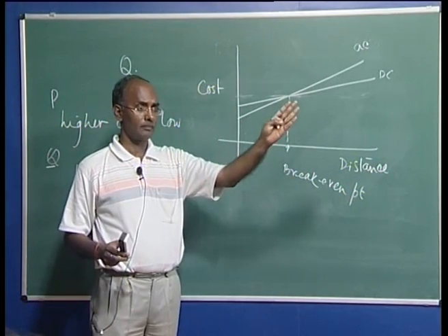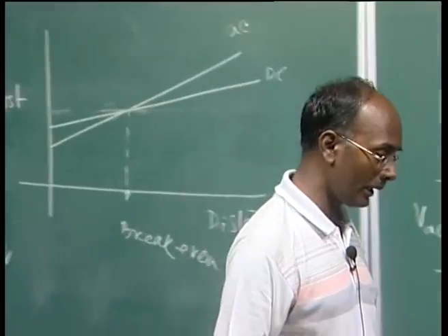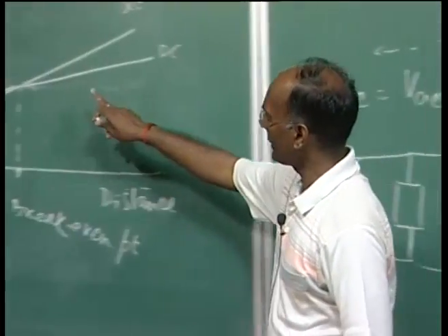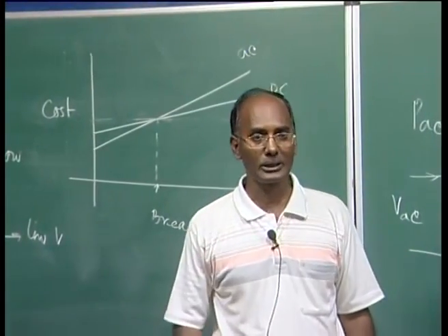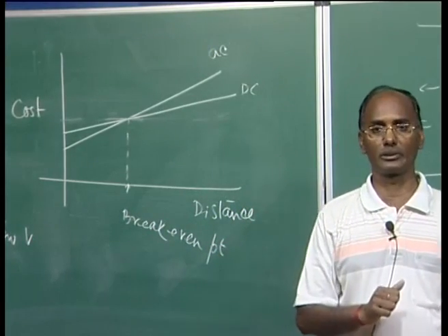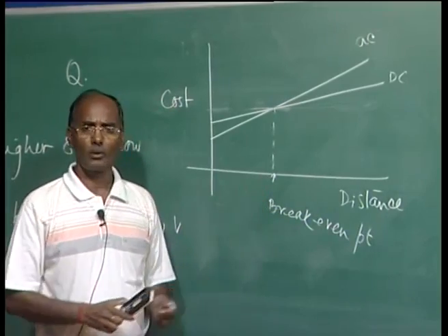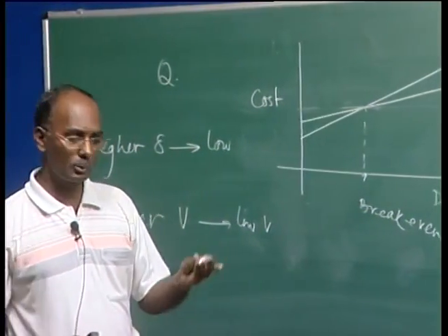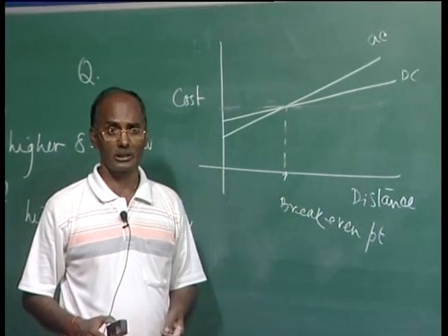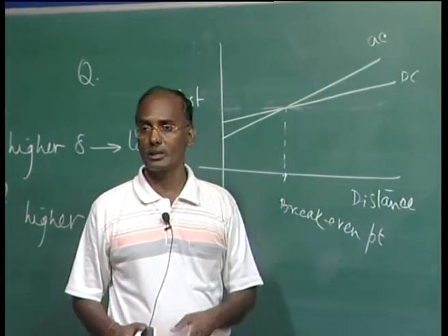But if you are going for a long distance, you will see AC becomes more expensive. Now the question arises, why does AC become expensive if the distance increases? This is only because as the AC distance increases, you have to go for compensation due to the huge charging. You have to use intermediate station compensating devices to control the voltage in the transmission system, and thereby you have to have a substation, and this will be more expensive. Earlier the break-even distance was more than 800 kilometers, but now due to the advancement in power electronics devices, which are commercially cheaper, this distance has come down to even 600 kilometers. So if you are going for more than 600 kilometers, DC becomes a better option compared to AC.